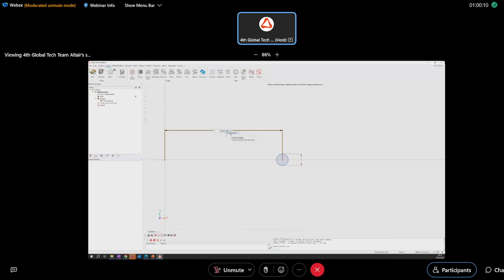And we can do the same. So we can create another variable. This variable cannot be used in SimLab 2024.1 in a simple way to perform DOE, but you can use these parameters with the script to perform multi-parametric analysis. So it's important to start knowing how to parameterize the geometry. Okay, so now we created two parameters, and we can have a look at them here because parameters are available in the parameters browser. We were in the assembly browser, where we can check the geometric entities, and in the parameters browser we have the parameters. You can check it, and we have L1 and L2 that are 1 millimeter and 10 millimeters.